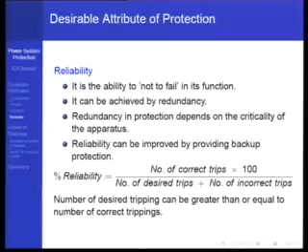You will have multiple protection systems, maybe of different philosophies, protecting it, so that a fault on it does not go undetected. For example, if you have a 400 kV line, you would typically have a pilot wire protection on it, or a kind of current differential scheme, and distance may be the backup protection for it.